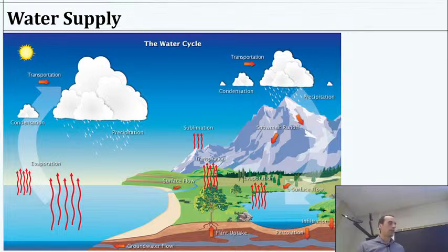Groundwater ties straight into the mountain stream idea. Groundwater is generally a good bet because it's going to have some natural filtration. Now, it depends a lot. If you're towards the surface, there's a lot of surface influences, and viruses and bacteria can be transported a certain distance into the soil, through the pores, all of that. That's going to happen. If you go deep enough, you're so far removed from human influences, assuming we're not injecting wastewater or something in the area.